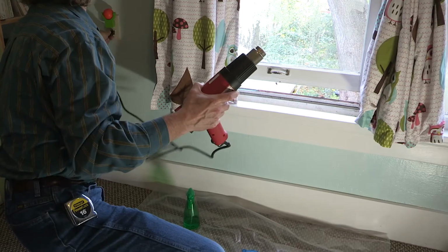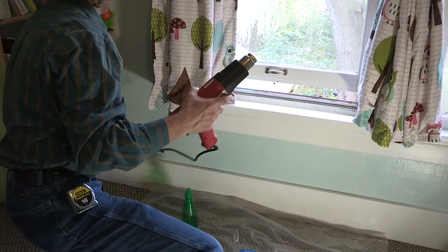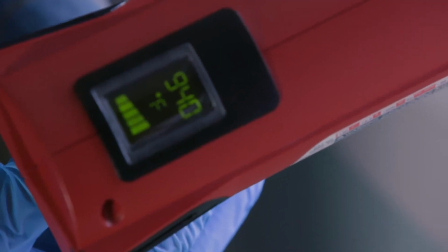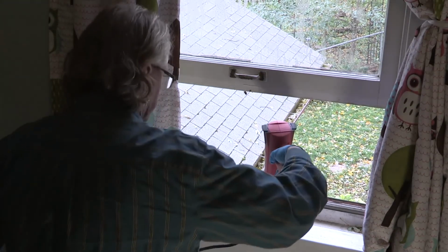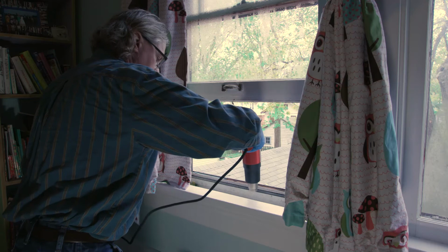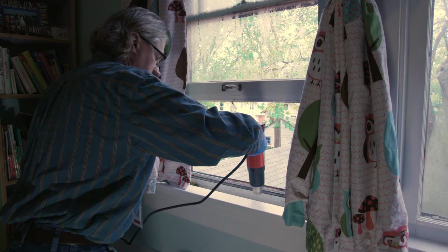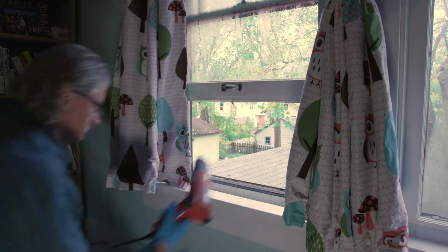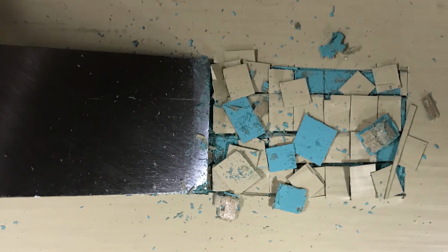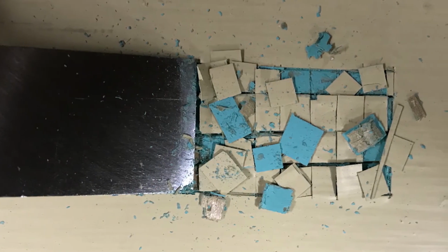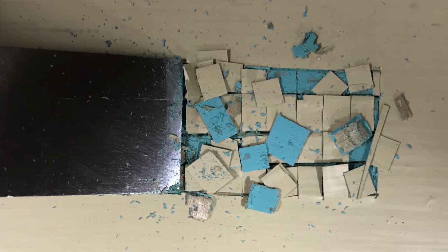Using a heat gun operated at less than 1,100 degrees Fahrenheit works the best for removing all of the paint layers with little effort. If you do not have a heat gun or are not able to use one in a particular location, score the surface several times in 2 different directions to form very small squares that can be removed. Using your chisel upside down helps to control the amount of substrate that is removed.